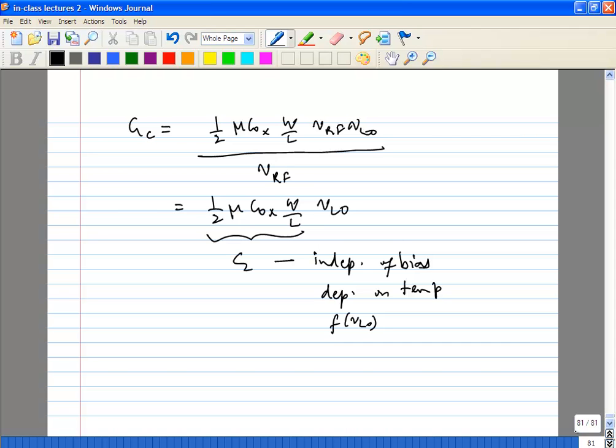We'll look at cases where you don't need to control your LO amplitude to a fine extent. That will come next. Because ideally you want that. Let's say you're designing a mixer of 20 dB. Then this puts constraints on your LO design. That means the LO signal coming in should be of a fixed amplitude if you want a fixed conversion gain. We don't want to give that constraint.